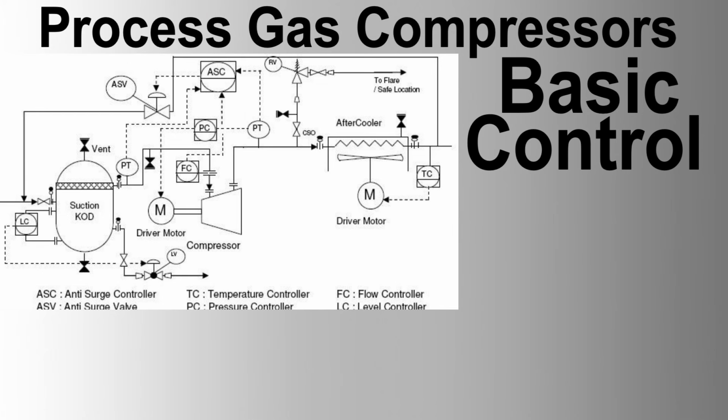The VFD may also be adjusted to decrease the compressor speed, reducing the pressure ratio and avoiding surge. 5. Stabilization. The system continues to monitor and adjust until the compressor operates within safe parameters, preventing surge.